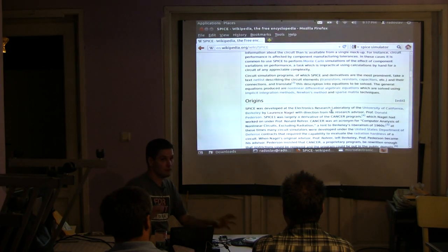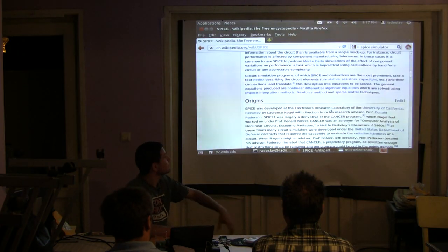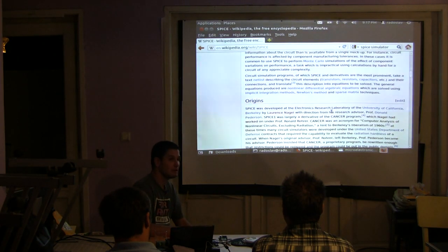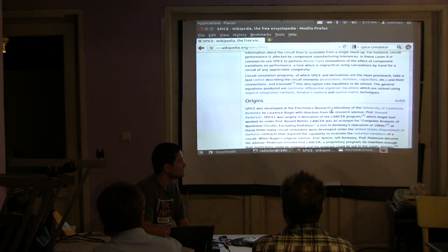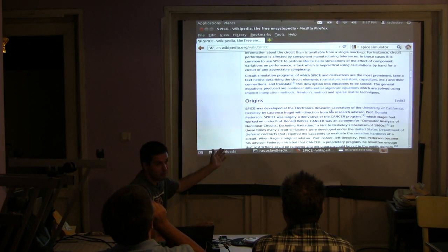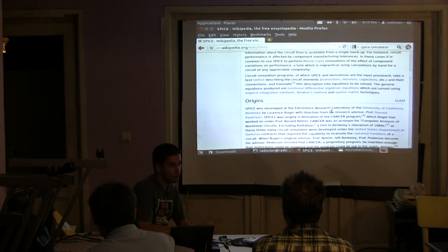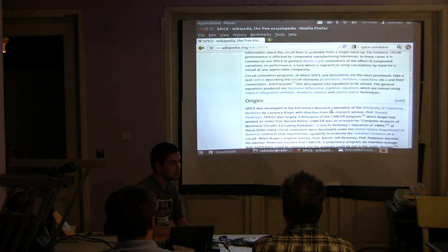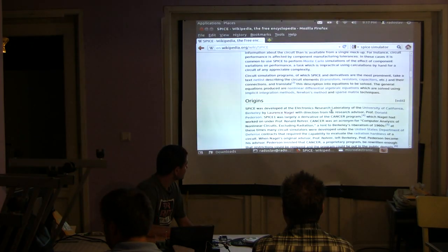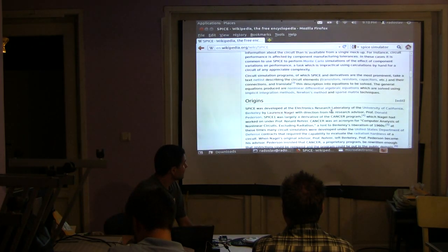The idea is to have a model, put some parameters in it, place it in SPICE, and at the end you end up with some DC parameters like we view in Qucs, for example the voltage drop or the current dissipation. There are much more complicated parameters that are extracted from the currents and the voltages.